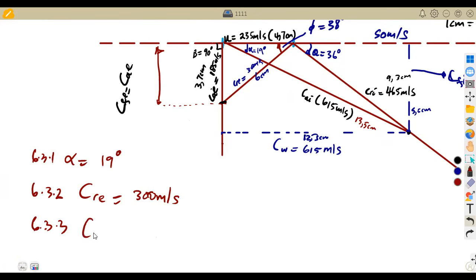So meaning to say we have the wheel velocity, the total of it, which is 615 meters per second. So these are the typical questions. That's how we might be given questions when it is discharging axially. The most important part that you need there is at the outlet, at the exit, you are taking this at 90 degrees. So the exit absolute velocity was taken at 90 degrees. That is how you are supposed to have this diagram.